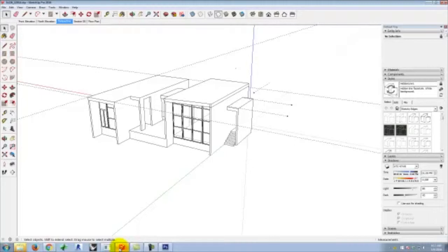Okay, so we cut a floor plan at 4 feet above the ground, which is right about here, because it cuts through the windows. If we cut a floor plan too low to the ground, it wouldn't necessarily cut through the windows. It cuts through the doors. It's not too tall to show where the doors are. And it's above the kitchen cabinets, so it's above your lower kitchen cabinets. So when we draw a floor plan, which you all did, you drew in where the cabinets were, where the sink was, where the toilet was, all those kinds of things. That's because we're cutting the building at that level.